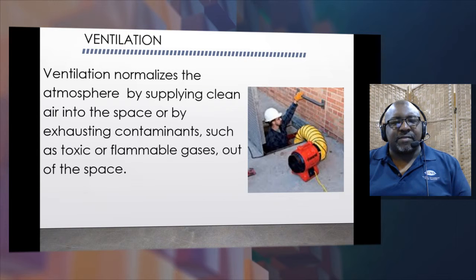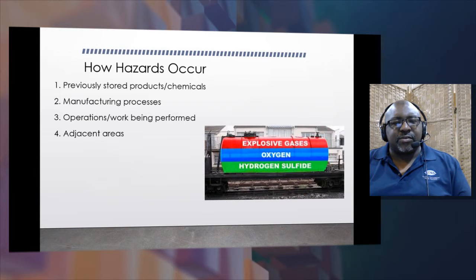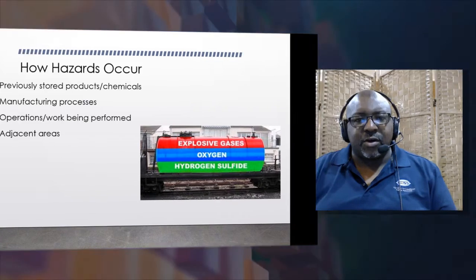And before we get into ventilation, I'm going to show you this over here again. When you're doing this monitoring, you're not letting your meter go down. You want to make sure you have a long enough hose with one of those wands that will collect and channel the gases through the wand, through that filter, into your monitor. So make sure that you're not dropping the monitor, raising it real quick, and trying to get that reading. That's not how it works. So you want to actually lower your wand that is connected to your meter.